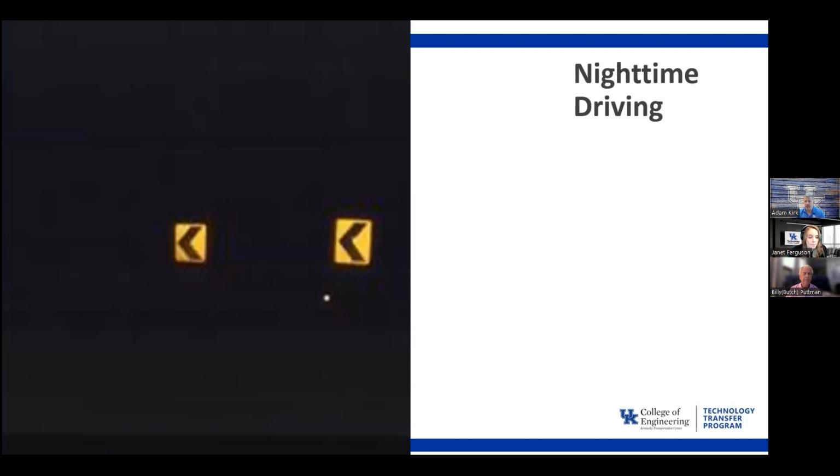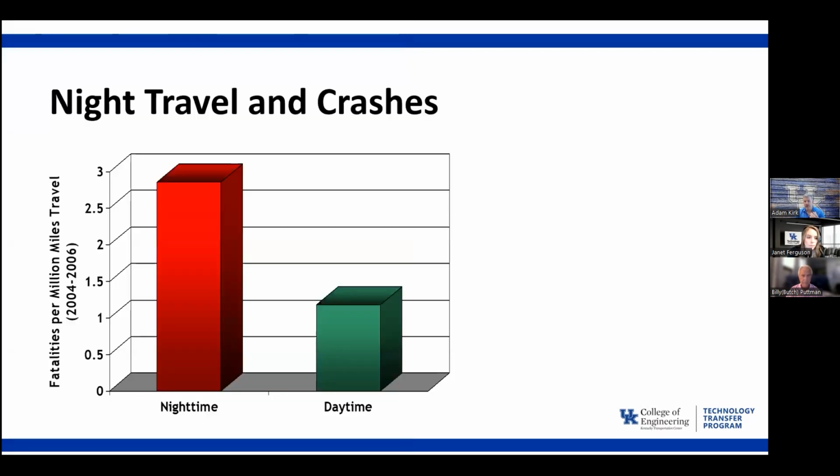So it's very important that signs are properly maintained, that they're not worn, and that we don't have any of that sheeting starting to delaminate, so that we still get good reflectivity off of it. That's what we need to make sure we do with our signing. One other thing: if you look at nighttime crashes versus daytime crashes, based on how many miles we drive, you've got about a 3 times higher chance of getting into a crash at night in these rural areas than during the day. While a lot of factors go into that, like being more tired at night, a lot of it is the visibility of that roadway and the directions we're giving. Signs can play a huge factor in making sure everybody's aware of where they're at on that roadway and what that roadway is doing.